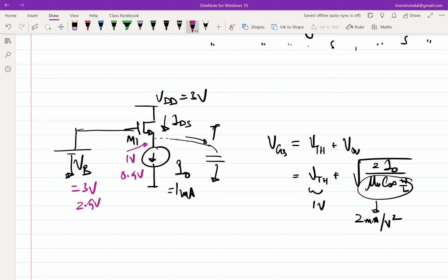Which means that if I, let's say, make VB equal to 0 volt and negative voltages are allowed, then can you comment on the source voltage? It will be -2, right? Source voltage will be 2 volt lower than the gate voltage, right? And if I don't want any negative voltage, then what is the constraint? Then VB has to be greater than 2 volt.